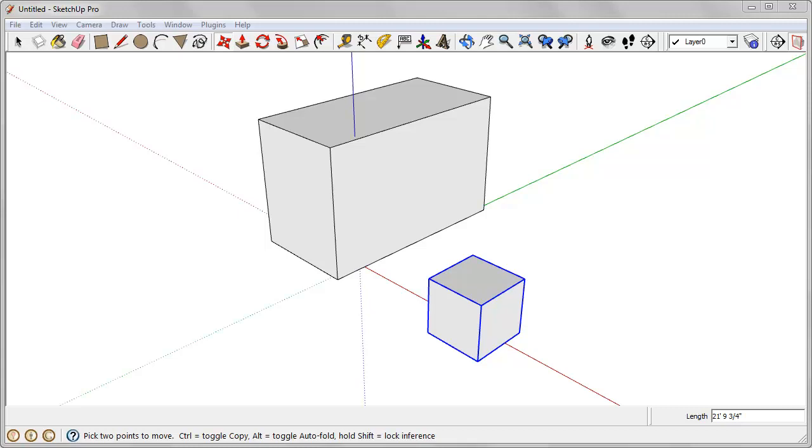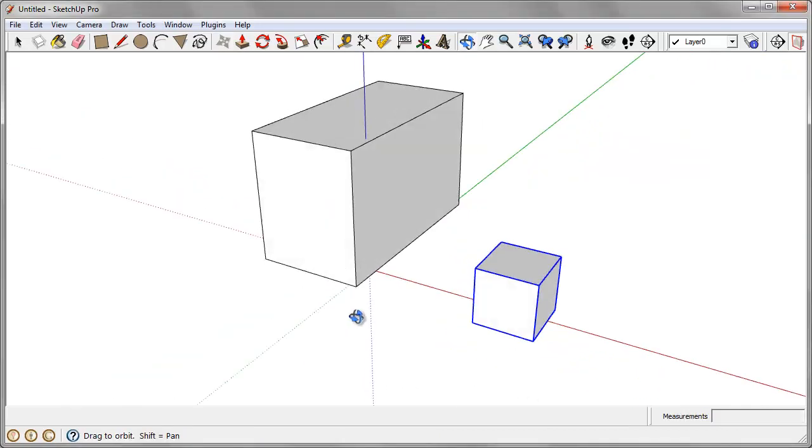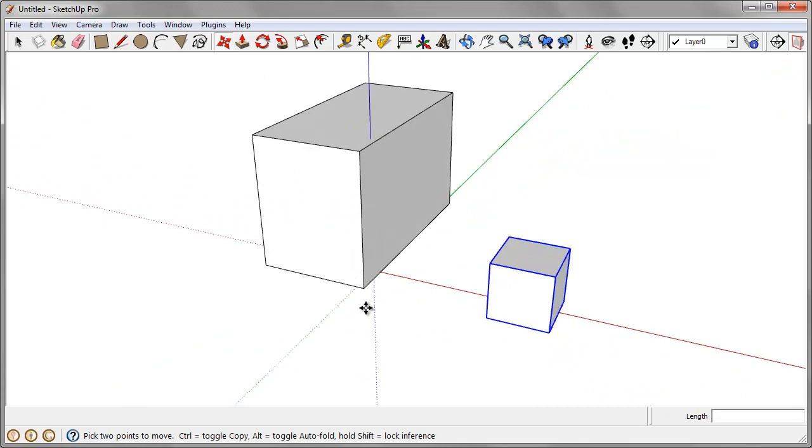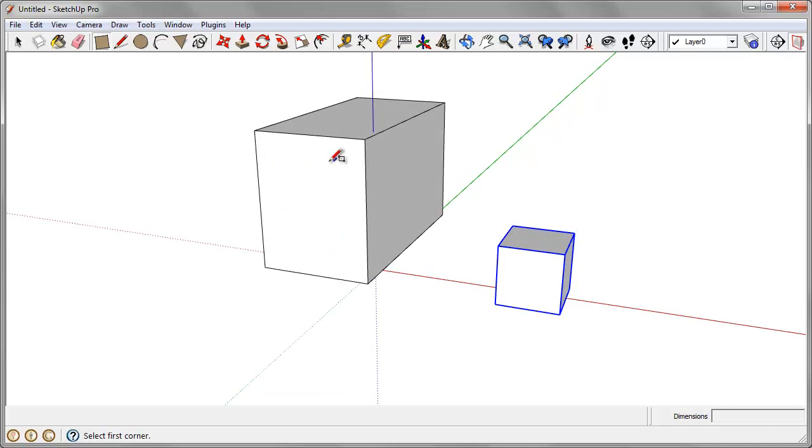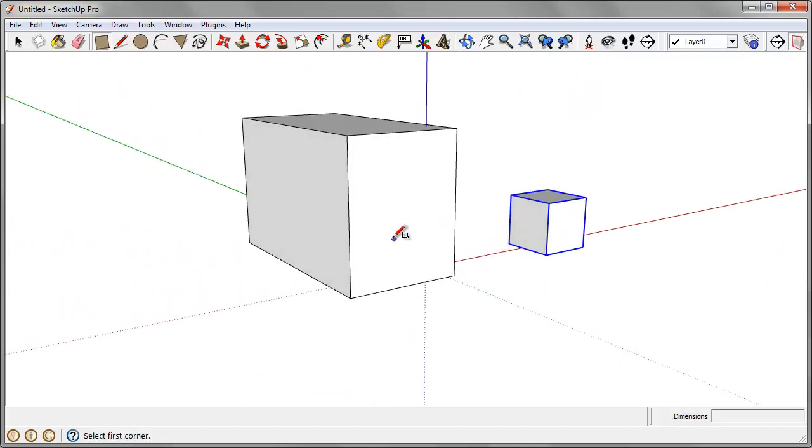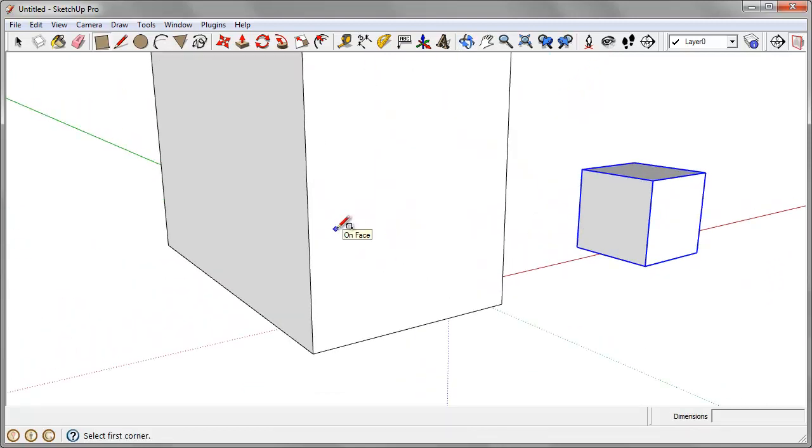So to create a component, we're going to say that this is a townhouse. So let's go ahead and draw a rectangle on the front of this townhouse to create a window. So I'll just click once to start on the surface, move my cursor to suggest a direction, let go of the mouse, and let's type in, let's say 4 feet, 8 feet, enter. So a 4-foot by 8-foot window.